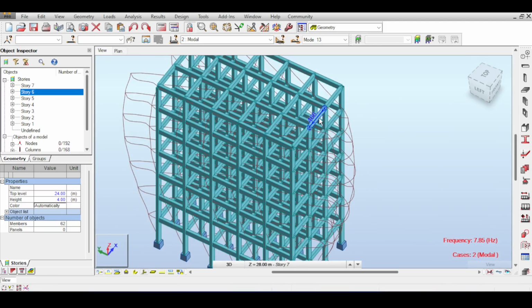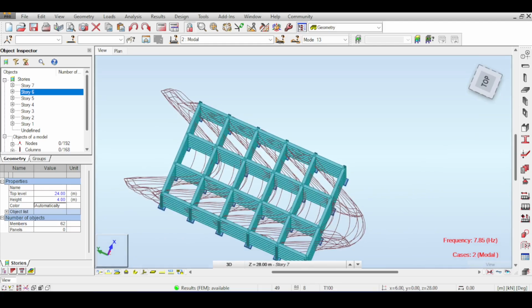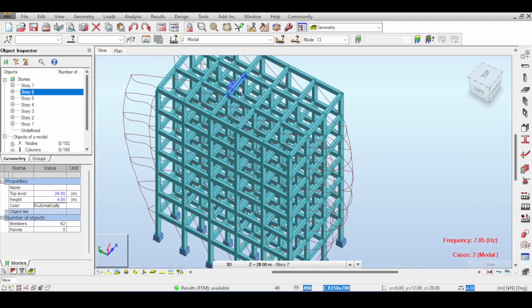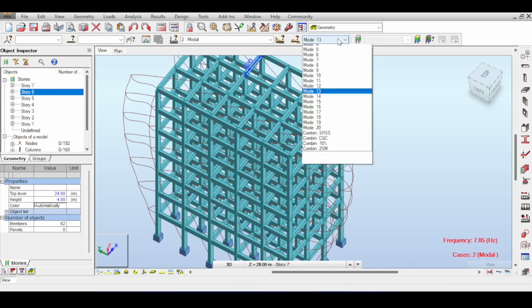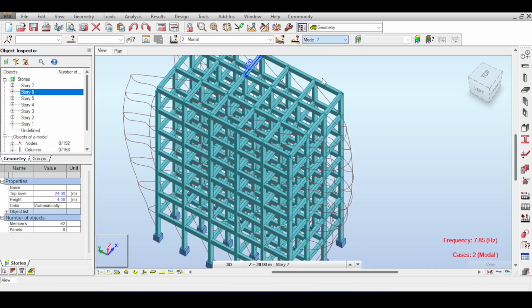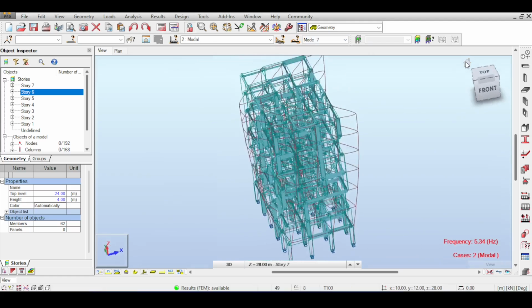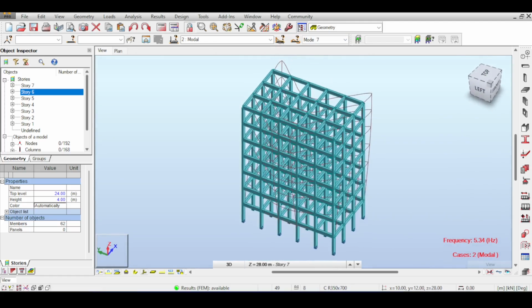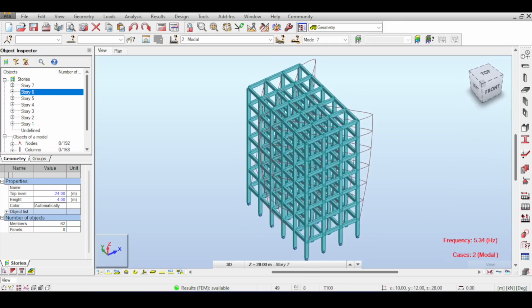And you know that stiffnesses have to do not with lengths, but with length square and length cube sometimes, and even higher powers of length. So the idea here is that yes, the column itself is easy to bend in this direction, but the beams are not. And a beam that is long is easier to be bent than a beam that is short. Now, the sorting of the modes is not exactly similar to the previous structure, but my conclusions still remain the same.